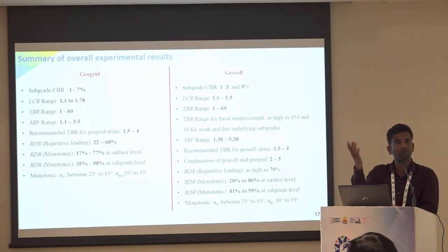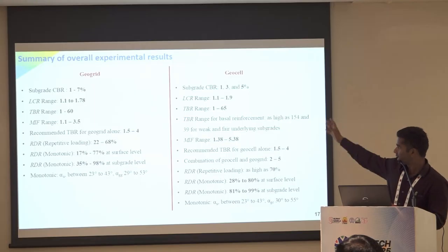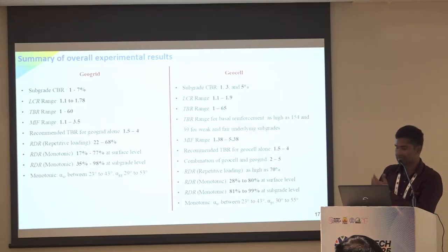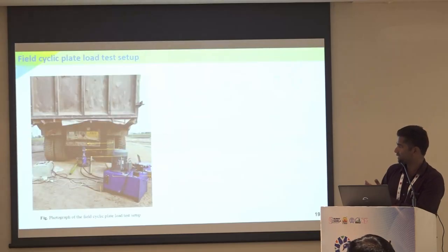Geocells are able to spread the load by up to 12 degrees at a maximum, in very favorable conditions. So these ranges have been done, and even Professor Madhav has done a lot of work on geocells. I think it's classical work they have done on the mechanism. We're trying to do some field tests as well.